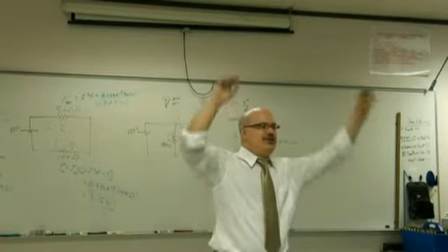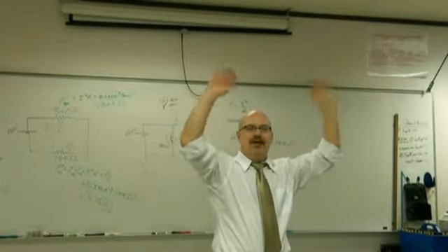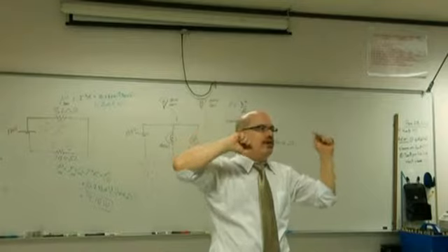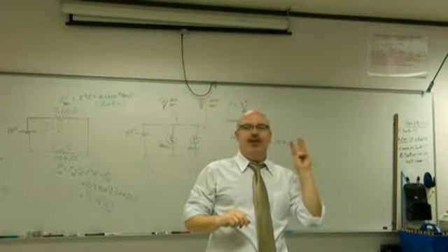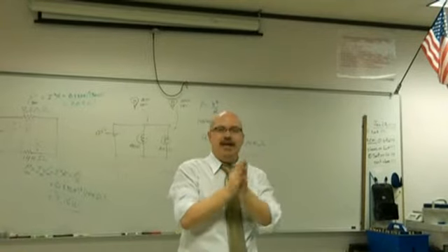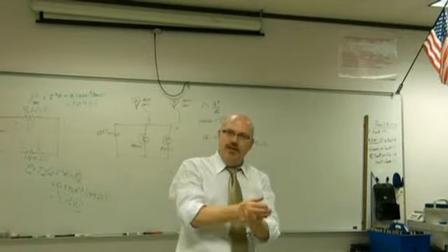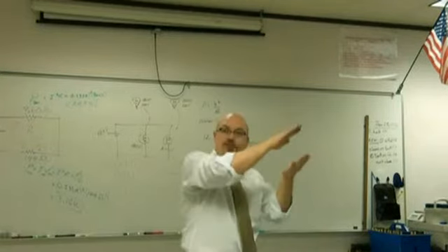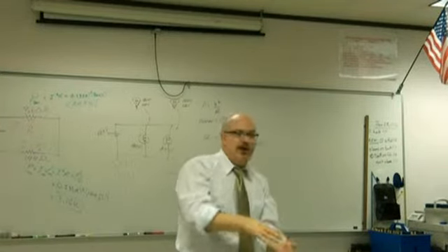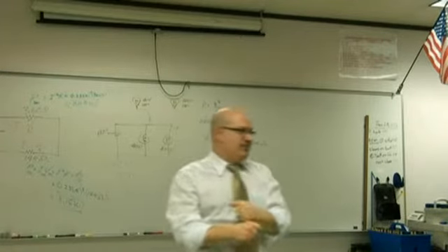All right, now listen. I want to heat the room up because it's cold. I have 3 resistors and I want to heat the room up. How do I hook up the resistors so that I get maximum heat? Hook them up in parallel. Parallel produces the lowest resistance, therefore maximum current, therefore maximum power.